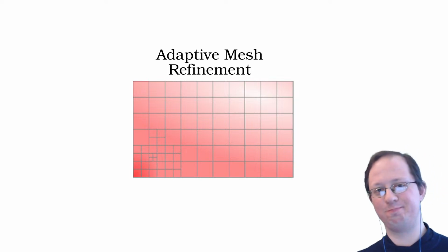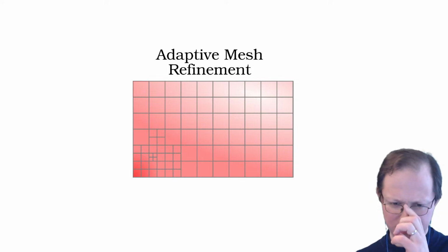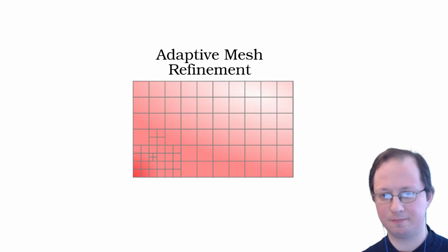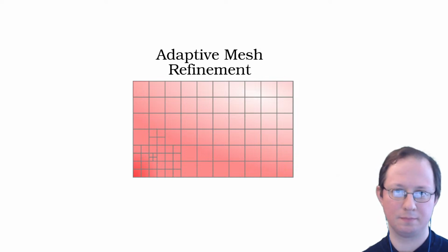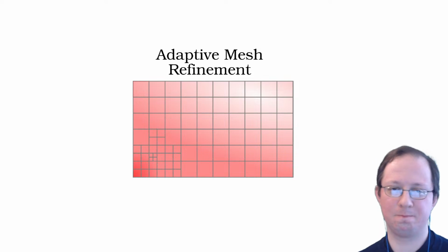And it also makes it more difficult to set up the octree, especially in a dynamic manner. When you really want dynamic adaptive mesh refinement, where fine grid cells are created dynamically in regions where there are super tiny vortices, and then coarsened again whenever a vortex has passed by and it becomes a more boring area of flow again, the memory management there is really difficult.